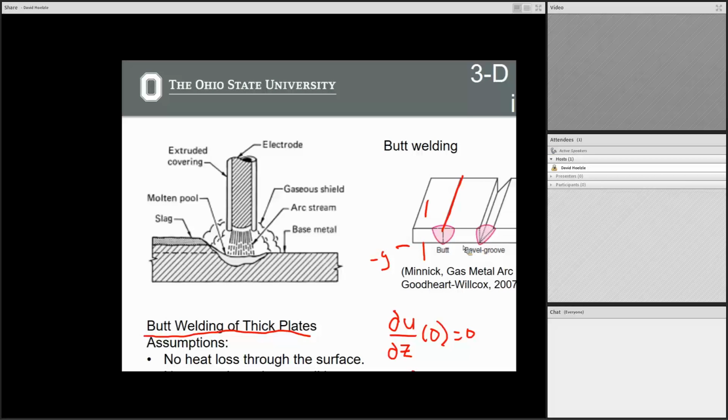That's the basic argument they're using here. They're saying, let's make this really simple on ourselves. Let's take a case where the bead that we're welding is very small compared to the entire plate. That is now an infinite plate. Now, this example from this book would be a case where your weld size is actually pretty large compared to the width in this direction.